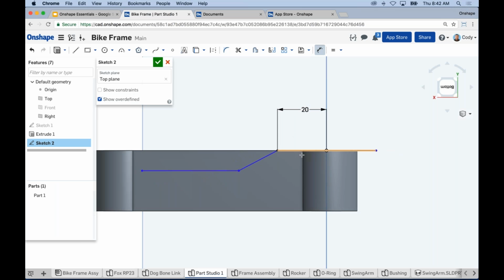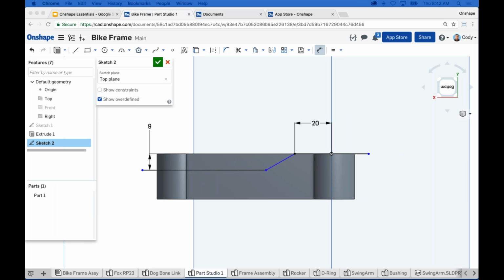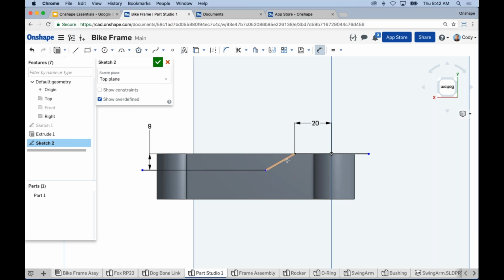So as I'm sketching, you can see I'm just adding simple dimensions to drive these 3 lines that I've sketched. Notice I'm not using any special tools for angle dimensions, for example. So I can choose 170 there just by left-clicking 2 lines that aren't parallel. It knows I need to add an angle dimension. And what I'd like to do here is take these 3 lines that I've sketched and offset them. Offset all 3 of them at once.